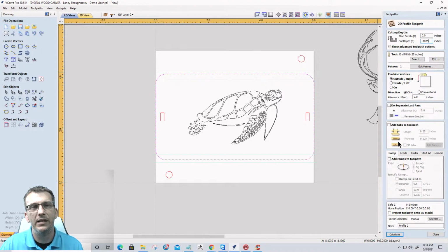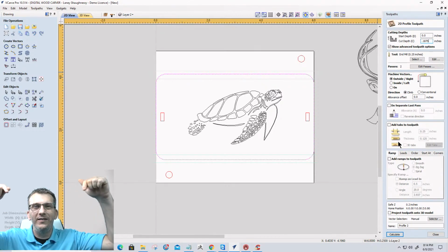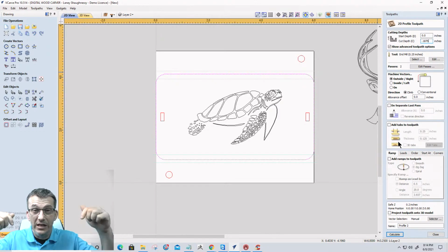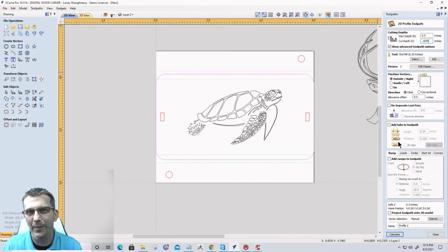And at this point, I've got to be mindful of my tabs. Tabs start from the bottom of the cut when you're cutting straight through. And on the bottom of my box, once I get about 3/16 of an inch down, there's nothing down there. There's nothing at the bottom of that cut for a tab. So on this type of project, to eliminate the need of tabs, I would probably use two-sided tape, or painter's tape and CA glue, or something like that.